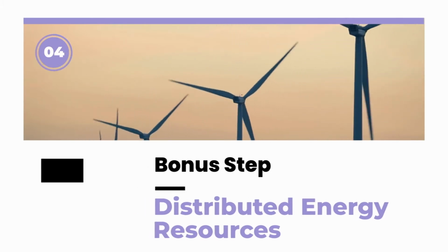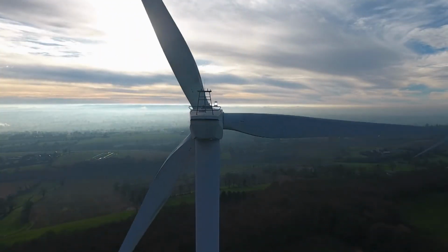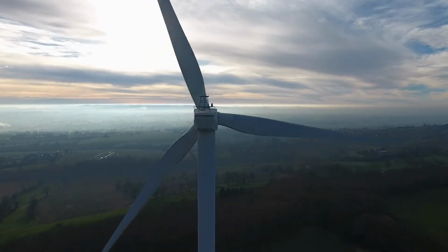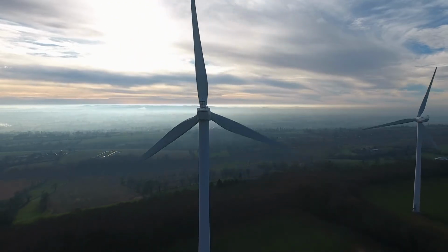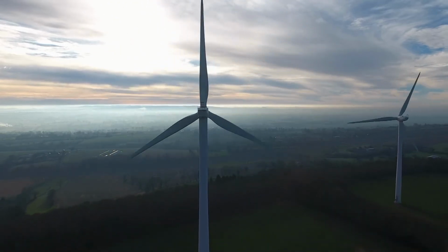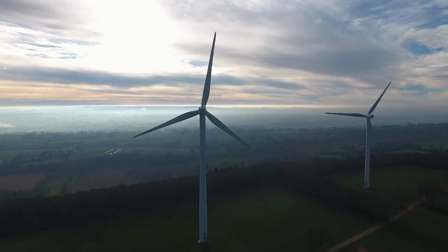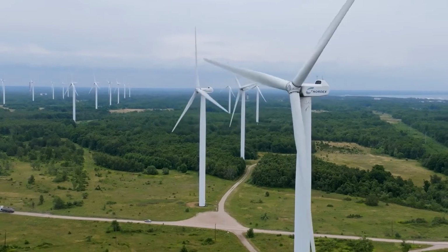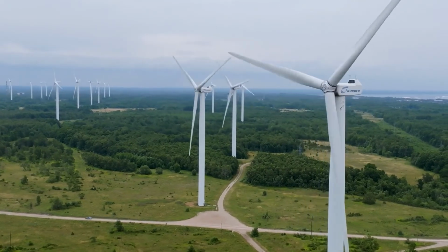Distributed energy resources, or DERs, are sources or sinks of power located on the distribution system, any subsystem thereof, or behind a customer meter. DERs include electric storage resources like batteries, distributed generation like photovoltaic solar, thermal storage, and electric vehicles and their supply equipment. In most instances, these resources are located close to the end user of power.